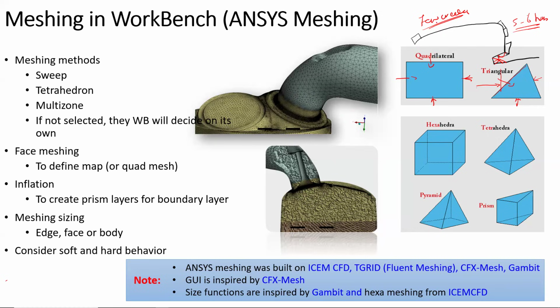So definitely, if you are able to make a high quality hexa mesh, a quad mesh, fine. Second thing is the quality, because with different geometrical features like sharp edges, we may not be able to produce them. So first, we have difficulty mapping the quads to the geometry. Second, it is difficult to have decent quality. These things are difficult to achieve with quad or hexa elements, but easy to achieve with the triangular mesh.